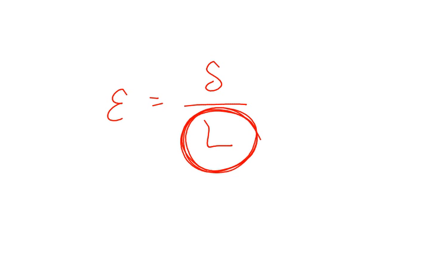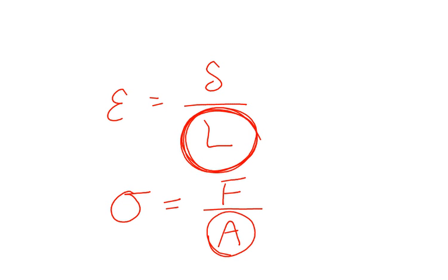Which is good, which is fine. But for stress, we take the force and divide also by the original area. These are all original values. Original meaning undeformed.